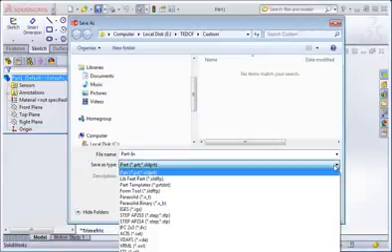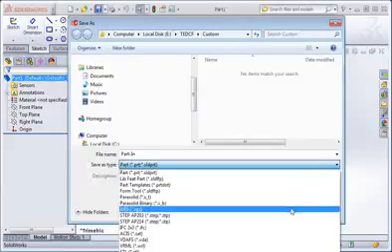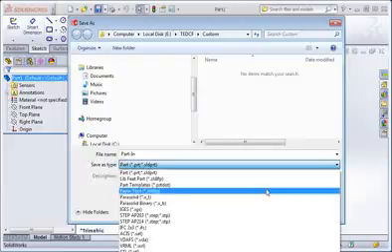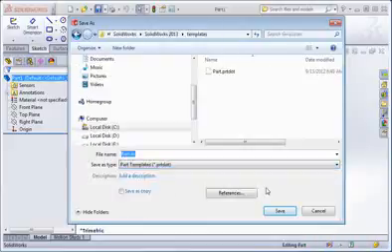Now click the down arrow on the Save As Type combo box. These are the types of files that SolidWorks can create from a part file. You can create IGES and STL files, and you can create Pro-E files. We're creating a part template, so select this option. When you change the file type to part templates, the Look In window automatically changes to the search path that has the highest priority, which is the path at the top of the list in the system options. So we'll need to change the priority so that our custom template folder will automatically be used.